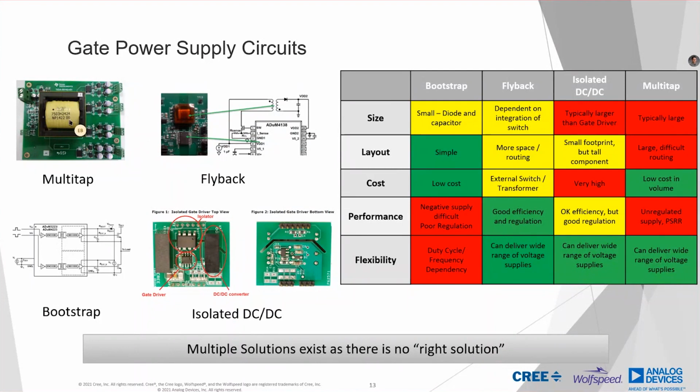The multi-tap often is the same flyback type thing. So you have a single transformer with a single driver. But now things get large. The transformer, instead of being small, gets to be quite large. And you can do different voltages, but now you can't regulate as much. You can only regulate for one of the supplies. So you get some trade-offs there. A common solution, especially from ease of design, is to use an isolated DC to DC converter brick. Okay, so now you get exactly the voltage.